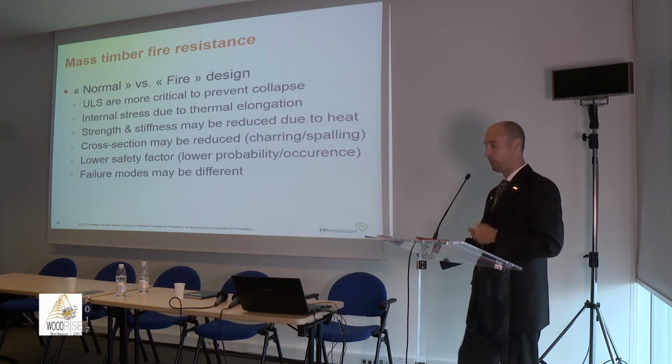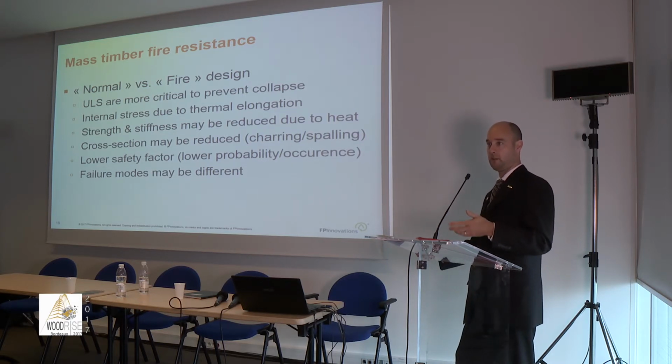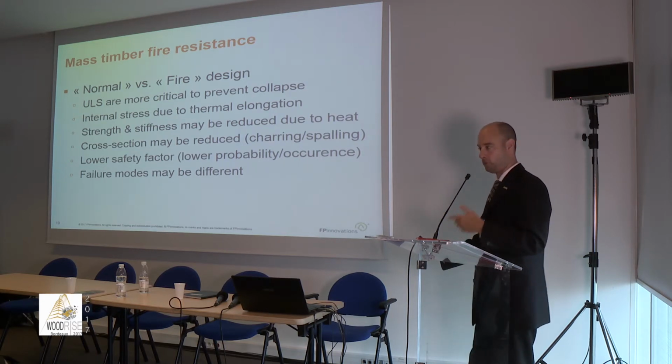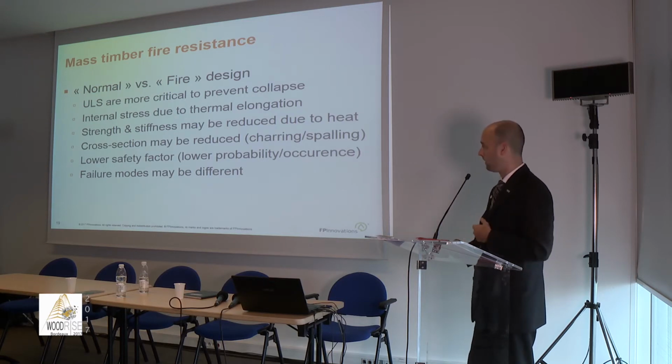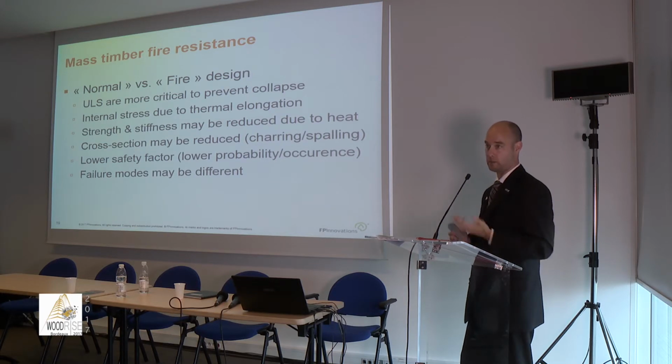If you combine steel, concrete, and wood, you may end up with some internal stress that you didn't encounter in your normal design. So for fire design, you need to consider them as well. You may have some strength and stiffness reduction because of the heat.